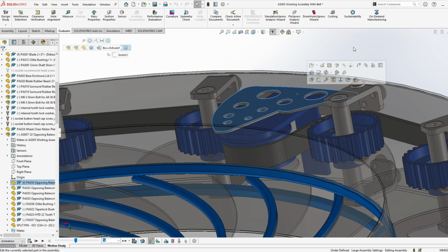bracket on Prototype 1, reinforcement was required, seen below the plate, to support the excessive forces on this HTD freewheeling pulley to make sure it doesn't buckle under loads. Also, this reinforcement helps make sure that this new tensioner part is mounted in the best way possible, so that the force applied to the enclosure is spread evenly across, seen by these flat pieces of 6mm stainless steel.